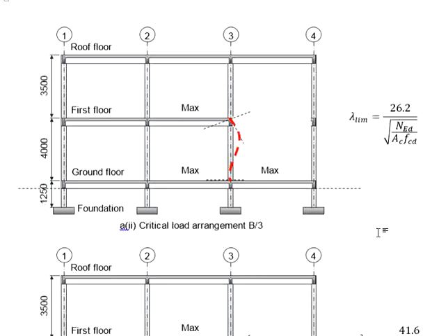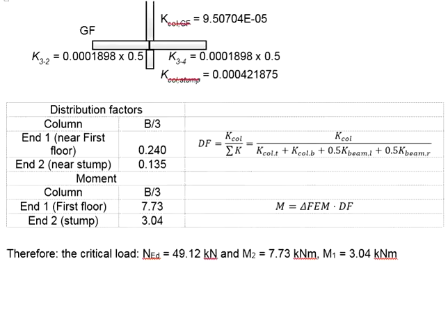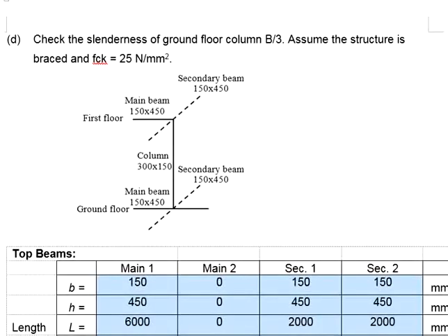Now it goes back to your design strategies and your assumption. You may also consider another aspect in terms of the moments acting onto the member, whether this moment is relatively large or small as compared to the sectional properties of the column.